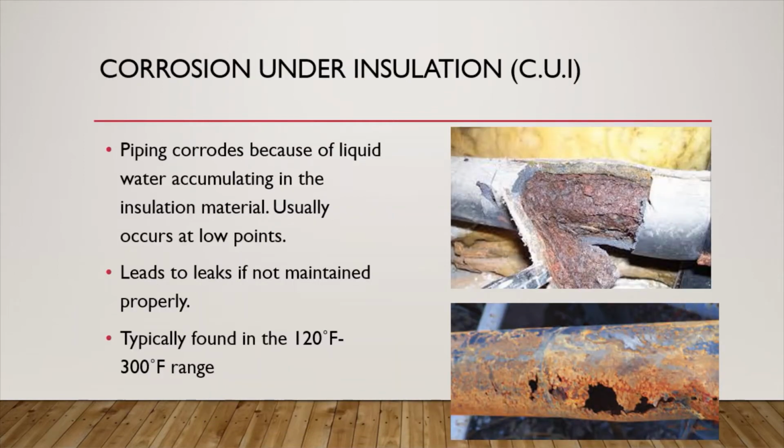Corrosion under insulation, or CUI, happens when an insulated pipe starts accumulating water, usually on the underside of the pipe, and starts corroding as a result. This thinning of the bottom side of the wall leads to cracks that weaken the material even further, and eventually starts leaking. Inspection of piping sections are frequently carried out to monitor the rate of corrosion in the pipe, and the standards will tell an engineer what the minimum accepted wall thickness will be for a certain size of piping.